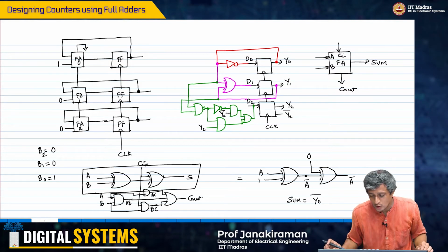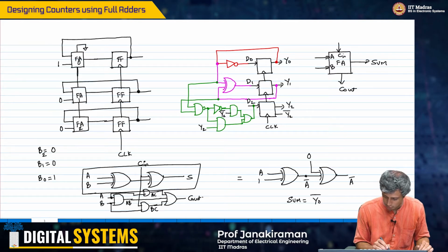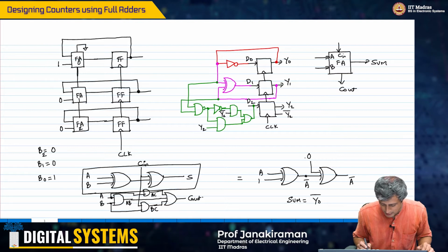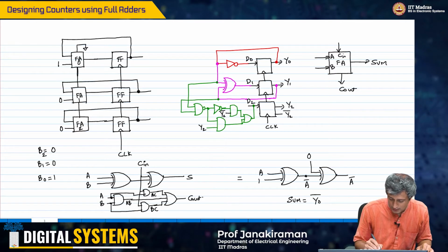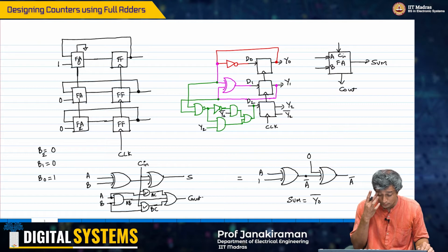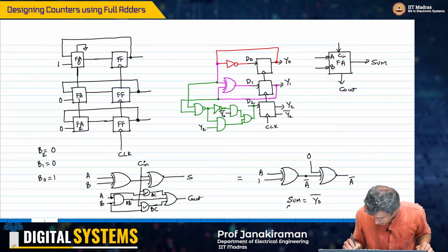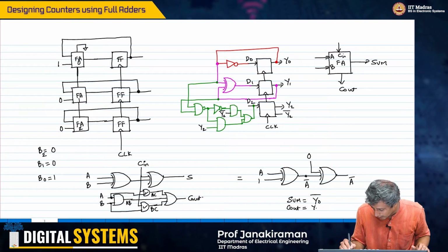The carry out of this particular circuit, right. So when B equals 1 and C in equals 0, okay, so I'll take this off. When C in equals 0, these two AND gates will give you a 0, and therefore C out will simply be equal to A, and what is our A input? It is equal to Y0,